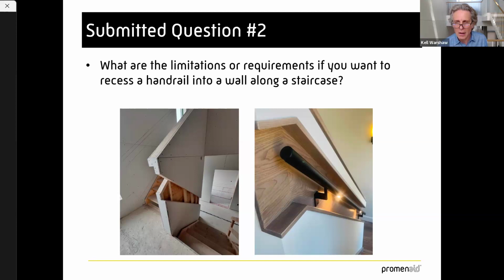There's definitely a potential issue when you mix stainless steel and aluminum because there's a galvanic reaction that happens where the anode and the cathode react and create electricity and corrode the material. What will always happen is the larger surface will be unaffected, and the smaller mass is the one that corrodes, because the electron flow is even across them, but it's all very concentrated in the smaller mass item and dissipated in the larger mass.